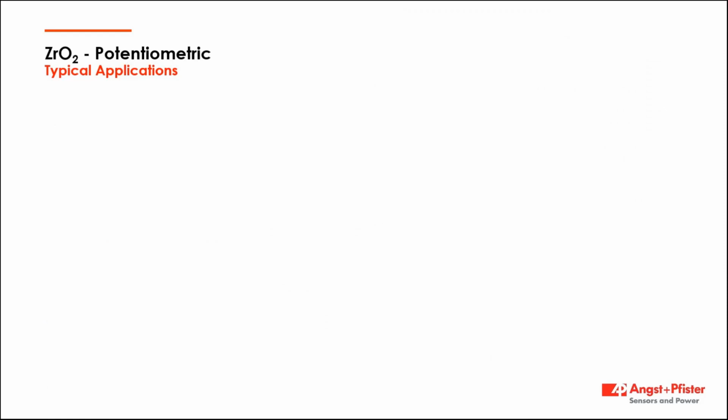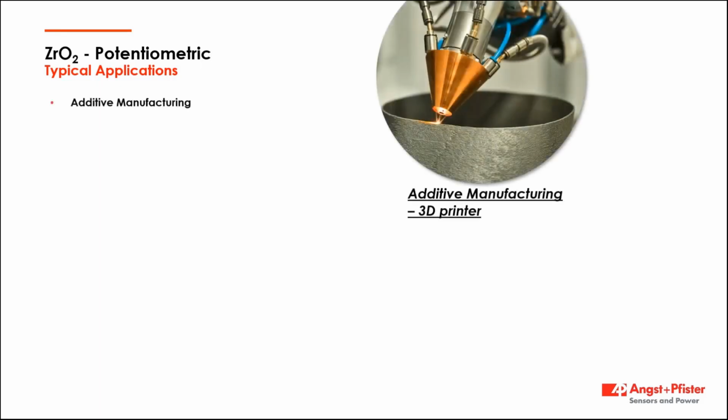Next, let's move to the potentiometric zirconia. One of the most interesting application areas for such type of oxygen sensors is additive manufacturing or metal 3D printing. Generally, this application requires a very accurate measurement of oxygen at lower ppm, parts per million, level, as the slightest amounts of oxygen present in the printing chamber can have a drastic influence on the printing quality. Such accurate measurement of oxygen at lower ppm levels can be reliably attained by the potentiometric zirconia oxygen measurement principle.